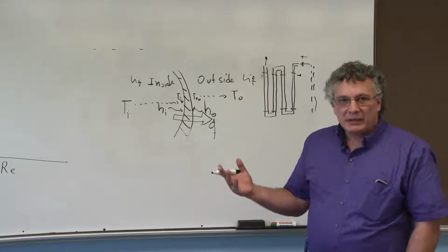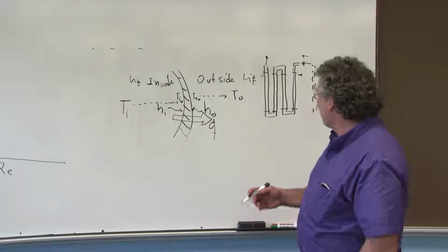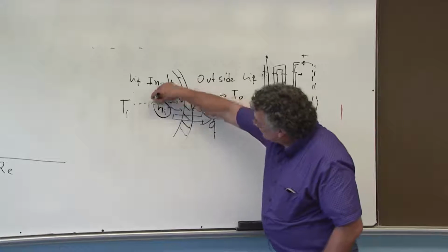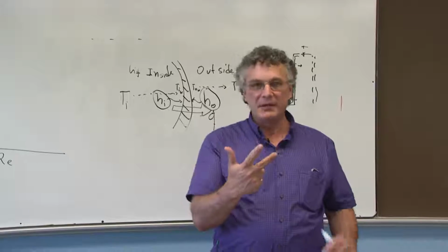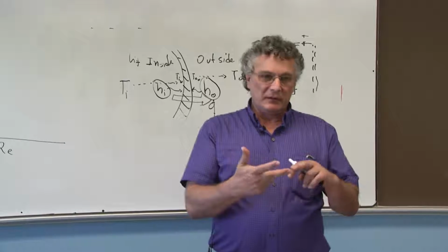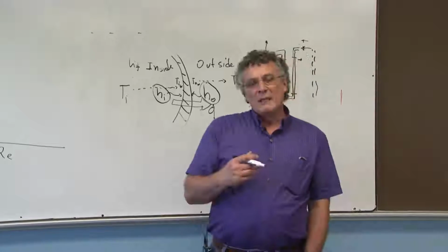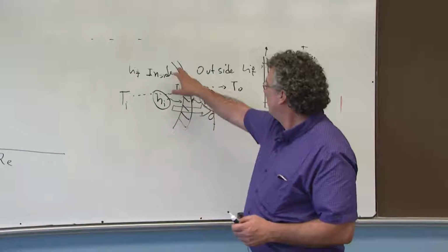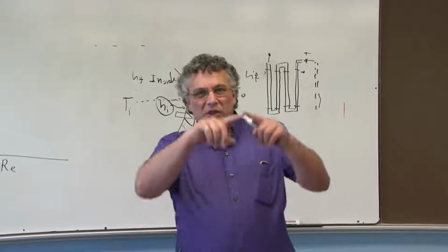That means the physical properties of that water are going to be changing during that trip. And you remember from your heat transfer that the heat transfer coefficient depends on three types of characteristics. The characteristics of the fluids. Specifically, the thermal conductivity, the density, the viscosity, and there are another set of properties, the properties of the materials, in this case the copper or the pipe or whatever, and the geometry, the diameter